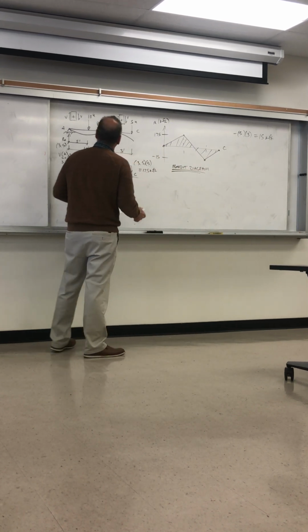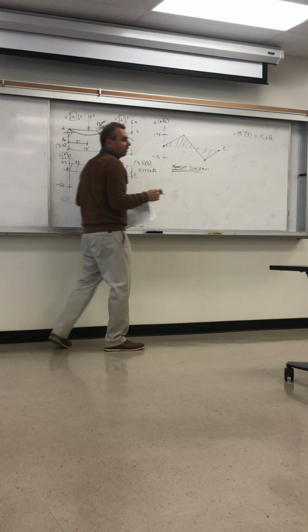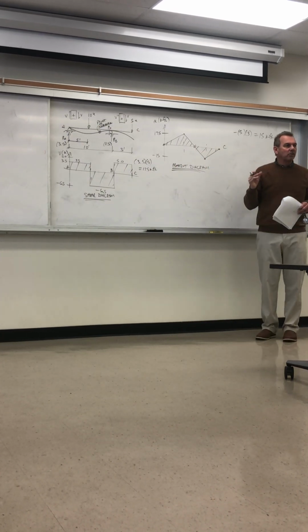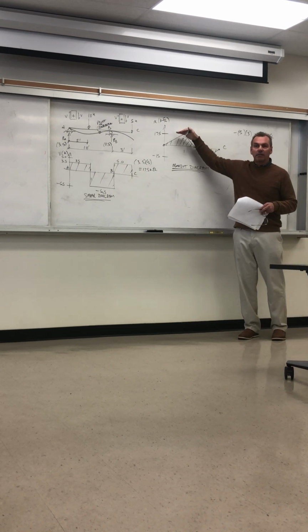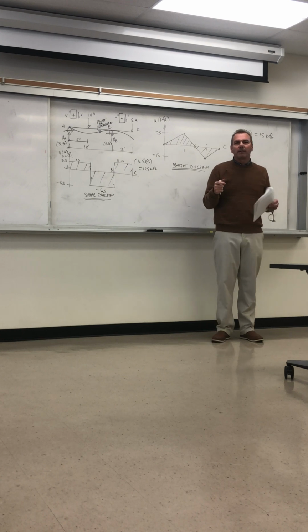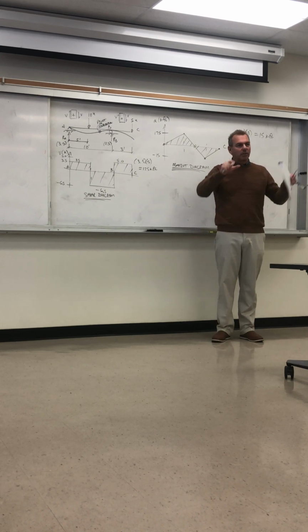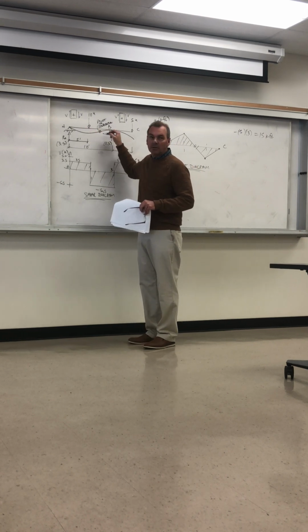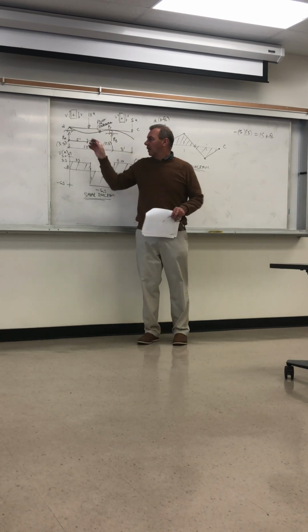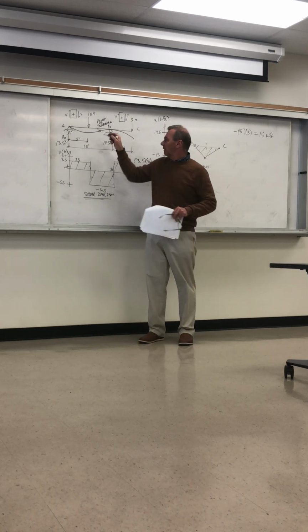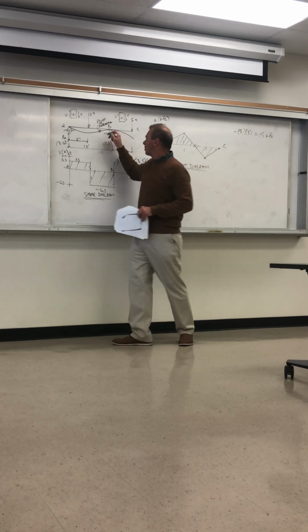And then we want to solve for this point of inflection, that's this point here. It's when the moment changes from positive bending, this is positive, to negative, right? Moment and curvature are proportional to each other. So the curvature is a change in slope with respect to x, so this is positive curvature, this shape that's downward like that is negative curvature.